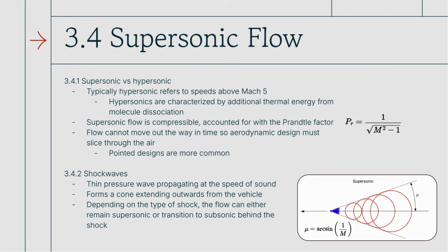The reason it's Mach 5 really just has to do with the amount of thermal energy in the system. Around Mach 5, you're going so fast that the literal molecules in the atmosphere start to dissociate. They can create a plasma if you're going really fast and strip the electrons out of their orbits. So essentially, you're going so fast that there's all of this chemical energy in that whole mixture. It can create a ton of heating, some really crazy conditions.